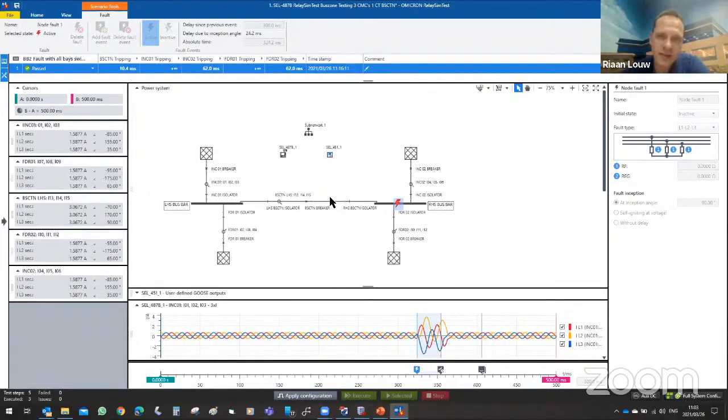because I don't have a second CT here to make sure that that fault is not here, what I'm doing here is implementing the coupler security. And remember, I explained this to say, I will have to make a decision. If I'm configuring my system to take speed as priority, I will trip zone 2. It will trip immediately all the zones to make sure that it's isolating this fault. Then you have speed. But if I want to have selectivity and isolate zone 2 accurately and not trip zone 1 for a fault in zone 2, then what I would need to do is apply the coupler security. Now, that is only done if you can live with a short delay on your operation.